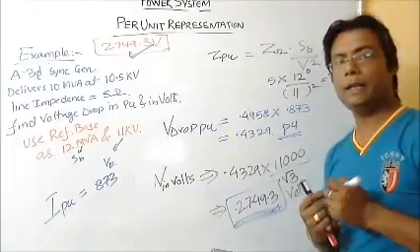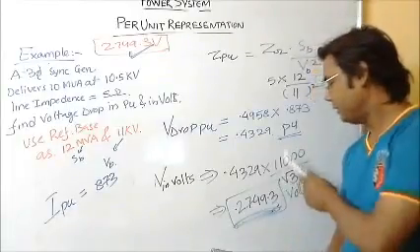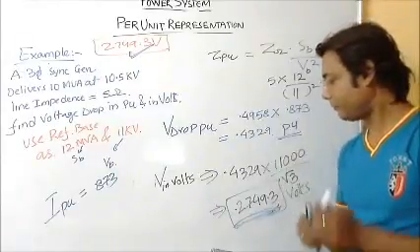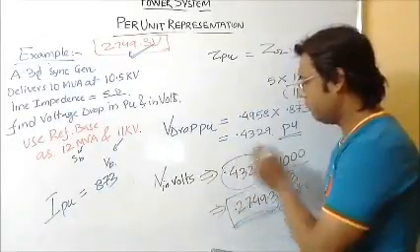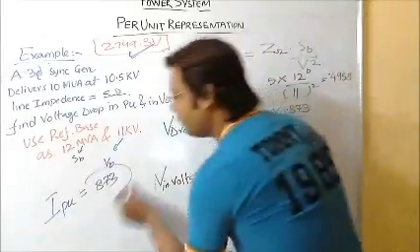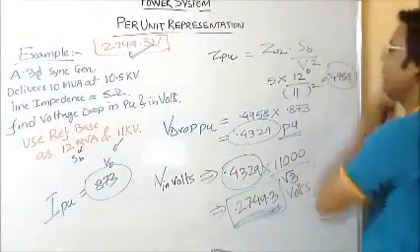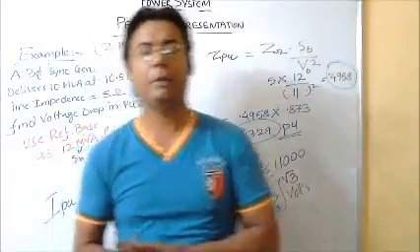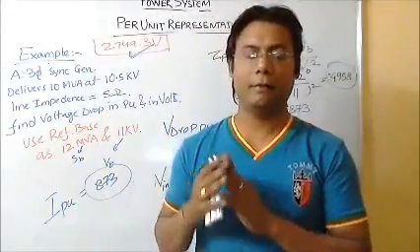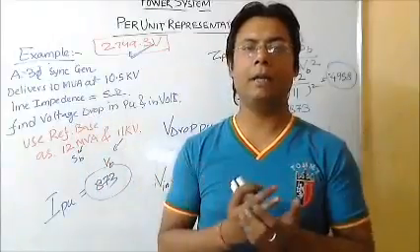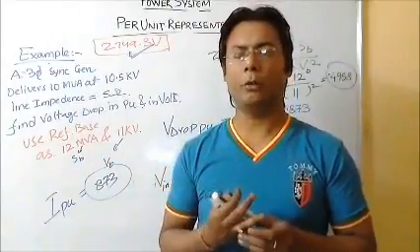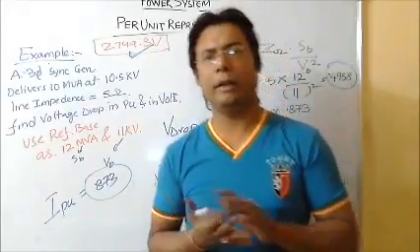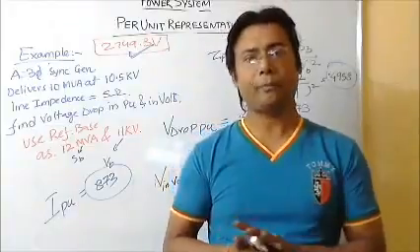So the values which we are getting in per unit, if we multiply by the base value, we will get the actual value. I per unit and Z per unit were in decimals. When all these values are in decimals, the value in a very large system will be at most 10 or 20, not more than that. So we can compute them by hand also.